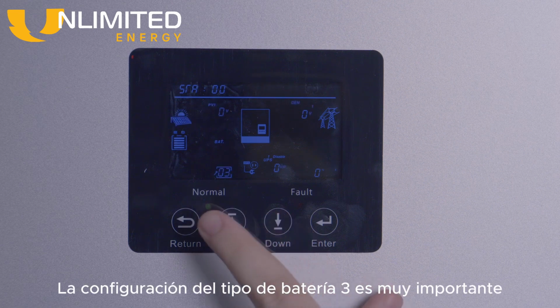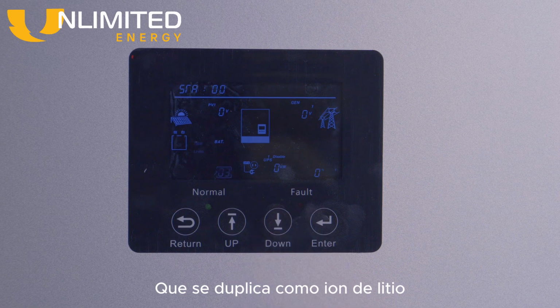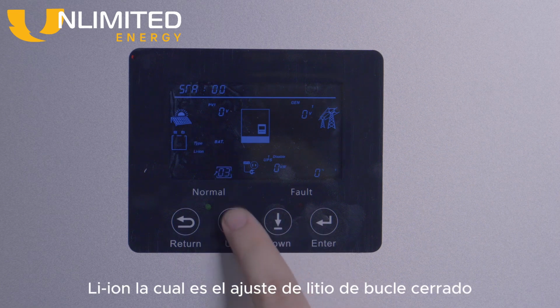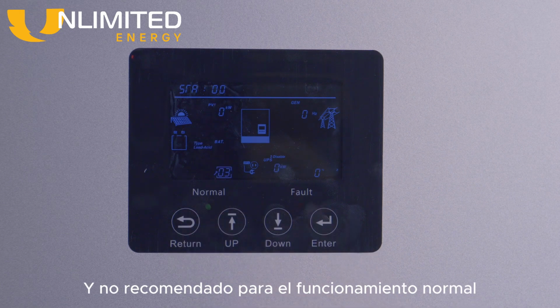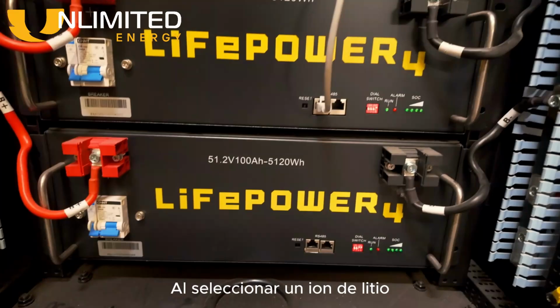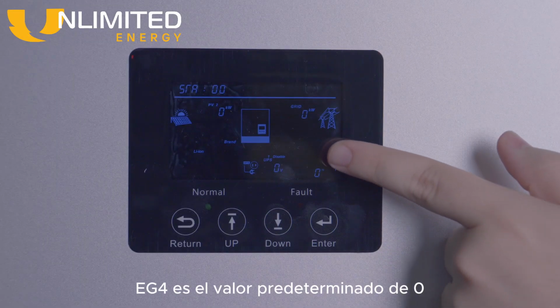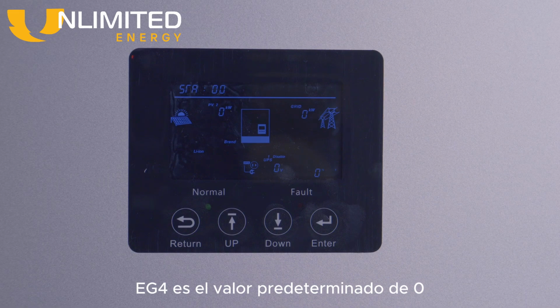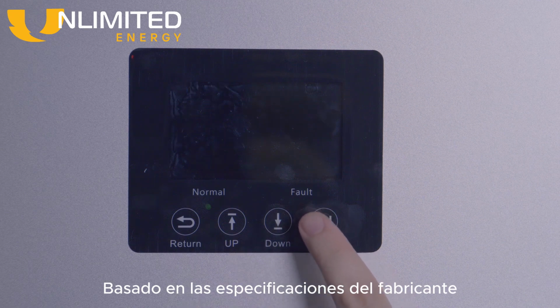Setting 3, battery type, is very important. This can be set to lead acid, which doubles as open loop lithium, Li-ion, which is the closed loop lithium setting, and no batteries, which is very niche and not recommended for normal operation. When selecting a lithium ion, you will need to input a battery brand. EG4 is the default value of 0. If you select lead acid, you will need to adjust the voltage parameters based on manufacturer specifications.